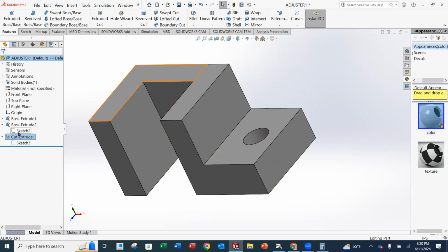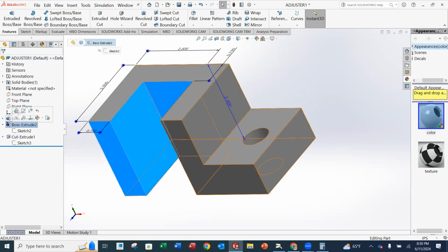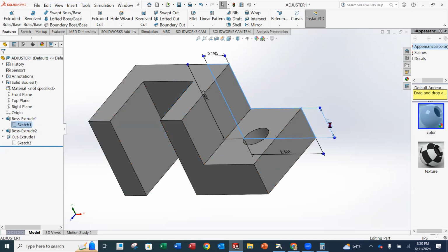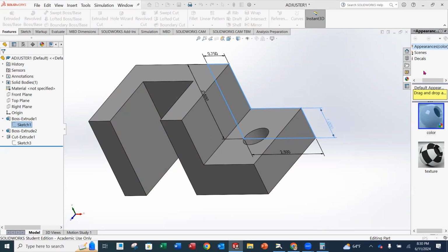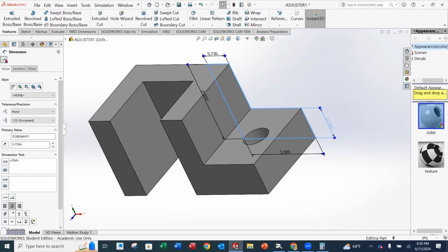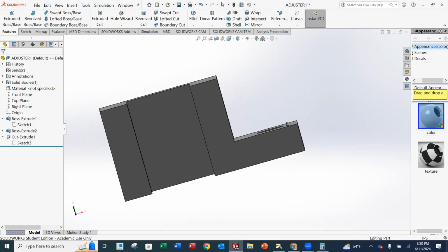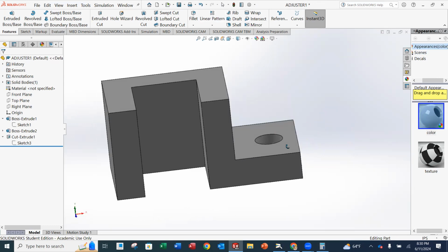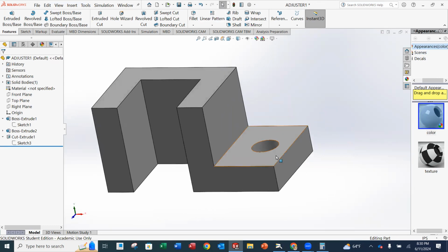So I'm going to go back up to, oh, not that one. This one. I'm going to go back to 3/4 of an inch, 0.75. And even when I change that, and I update that, notice that it's still going through as well. Okay. So up to next is a better choice than blind in that case, in case you ever envision that you could change a dimension here. Okay. So now I have all my features in place, right?